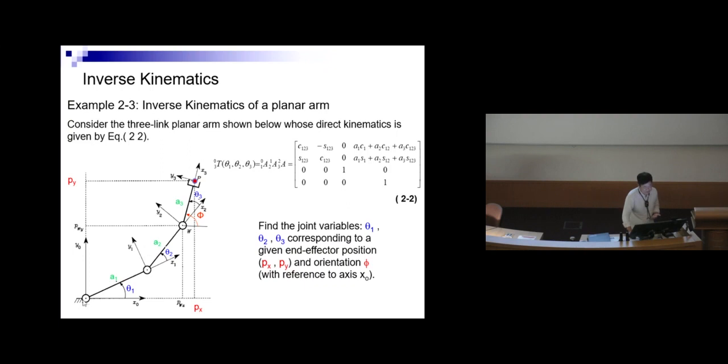This is the base frame, and you define your X over here. The Z-axis, the dot, is pointing out. This is your X0, Y0, and then you define your frames X1, Y1, and X2, Y2. This is the end effector point, an arbitrary point. You have a point over here, and you follow the link, so you assign it as X3.